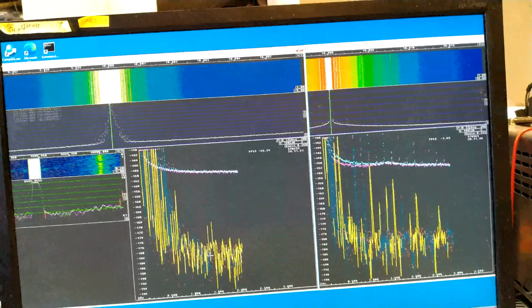The sound card has been running for 18 hours now, and I can see it is not flat in the same way as the SDR-IP pair is. It's running up to 20 kilohertz here. There are some little spurs, but nothing very strong until I come down to about 3 kilohertz here. And it's been running for 70 hours now.